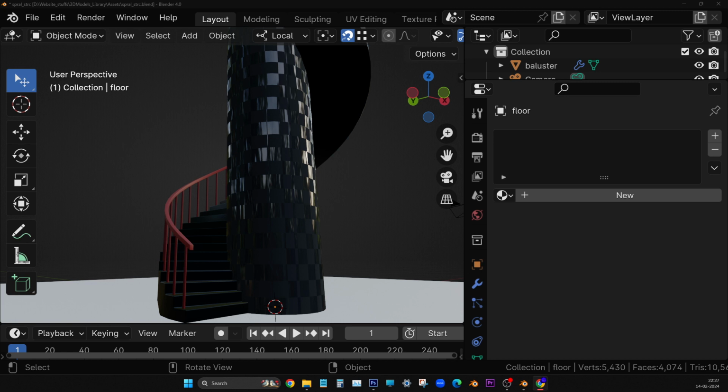Now select the top circle. Press Alt. Now right click, mark seam. Okay, fine. I don't know whether you did all transformations or not, so you can anyway do it again. But for applying all transforms, you have to be in object mode. Go to object mode and then apply Control A, all transforms. Right.